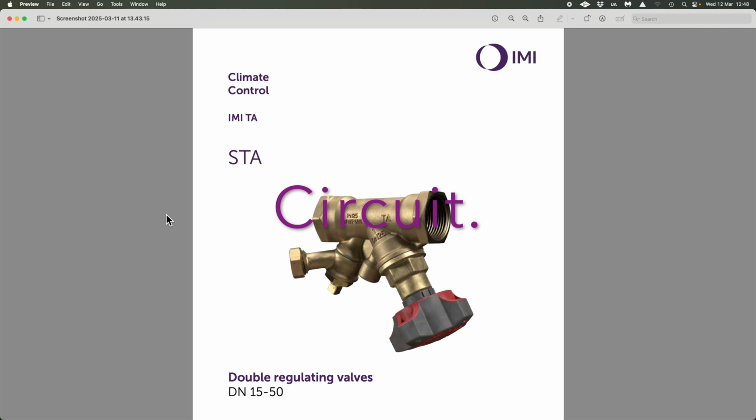So your pressure reducing valve upstream here set at say 1 bar, expansion downstream of this of 1.2 bar, and then this would be set at whatever your mass flow rate calculation is for your combination boiler, whether it's an 18 kilowatt, a 24 kilowatt, or 30 kilowatt, whatever it is, but we'll do some maths on that shortly.